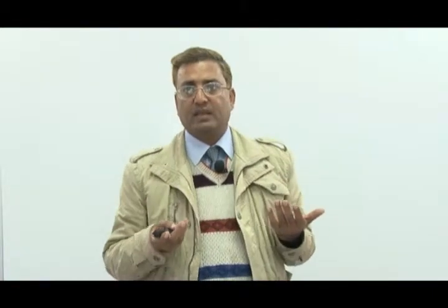Then there is the solid element of the 3D problem that we come across, especially for elasticity theory. It looks like this, showing the stress state. This shows the solid elasticity theory problem. This is the Belleville conical spring problem, where we have this kind of arrangement. One can see the pressure is applied from the top on this kind of spring. This is a geometrically non-linear large deformation problem, and an iteration method is generally needed for solving this kind of problem.